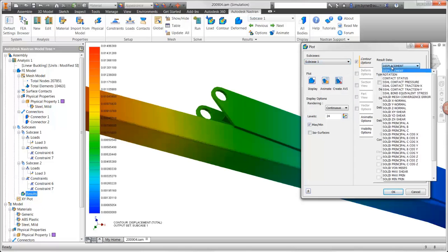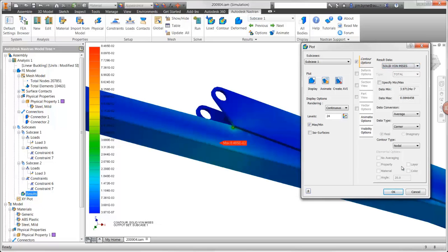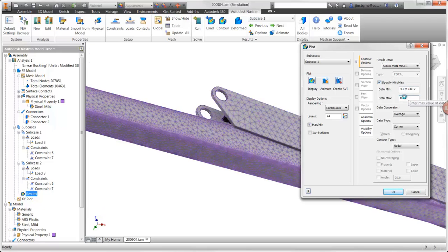We can also see that the stress results have decreased to a factor of safety of 2. Remember, this is only a 1 Newton load. The highest stress can be multiplied by 1500 to compare to the previous results.